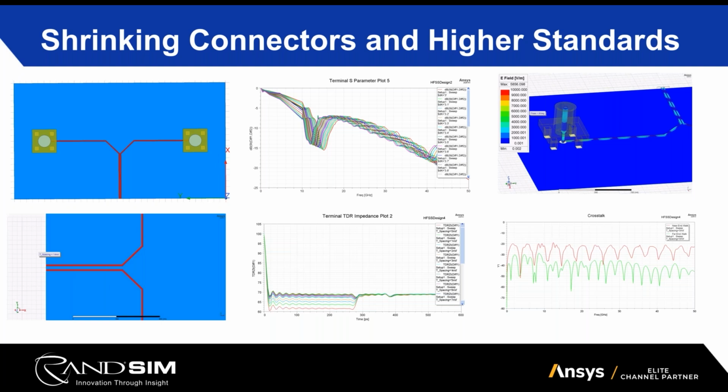This is really useful because what this is showing us is what dielectric constant is going to push our roll-off farthest. Now, using this is not only limited to materials. We also can do scans like this for things like geometry placement, thickness, things of that sort.